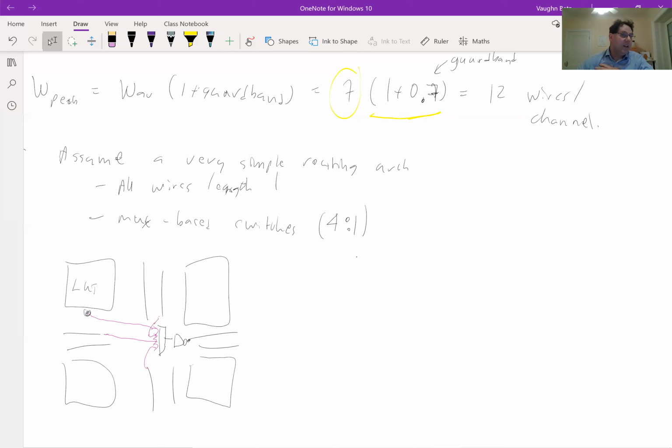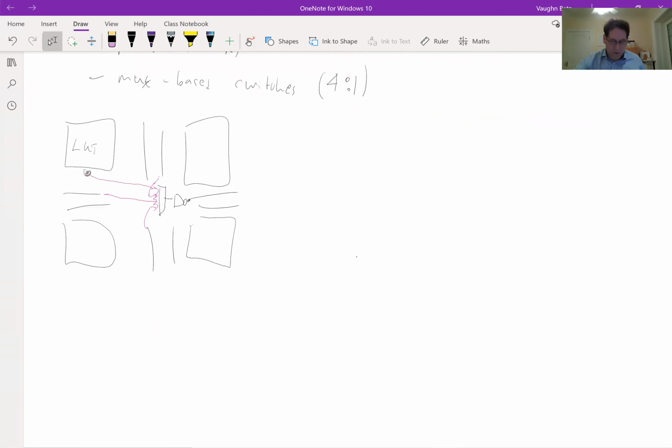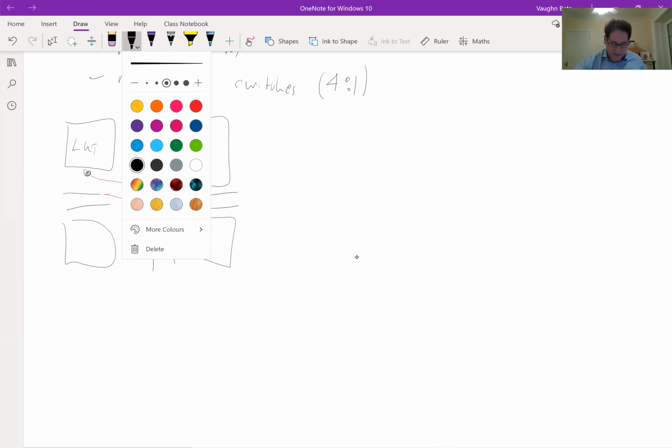The second question is a good question from Gil of, do you need the same channel width everywhere, or can you vary it? In theory, you can vary it, and there have been some studies saying that that is actually useful. It's really hard to lay out though. So almost all FPGAs, not all, but almost all, choose to keep the channel width the same everywhere, because it's much easier to lay out. And if you have some hard to route and some easy to route parts of the design, what you do is the CAD tools try to spread out the hard to route parts or interleave them with the easy to route parts. They can't do that perfectly, but it's just such a pain to lay out different channel widths that normally you just make it all the same. Okay, but good questions. So I have to watch the chat carefully.